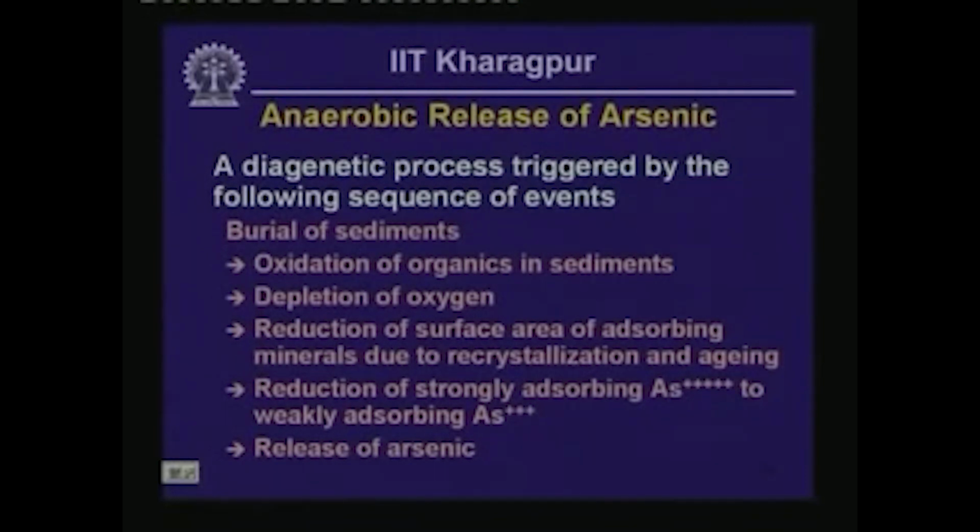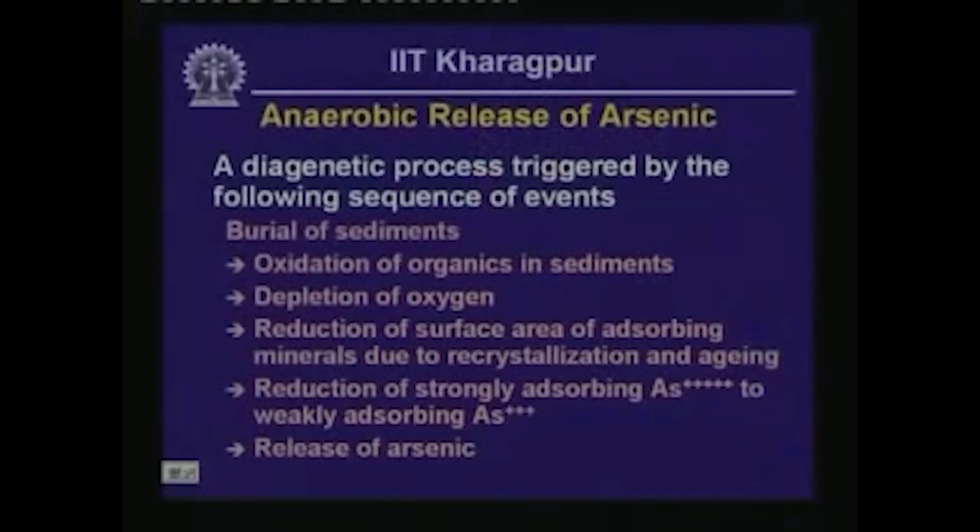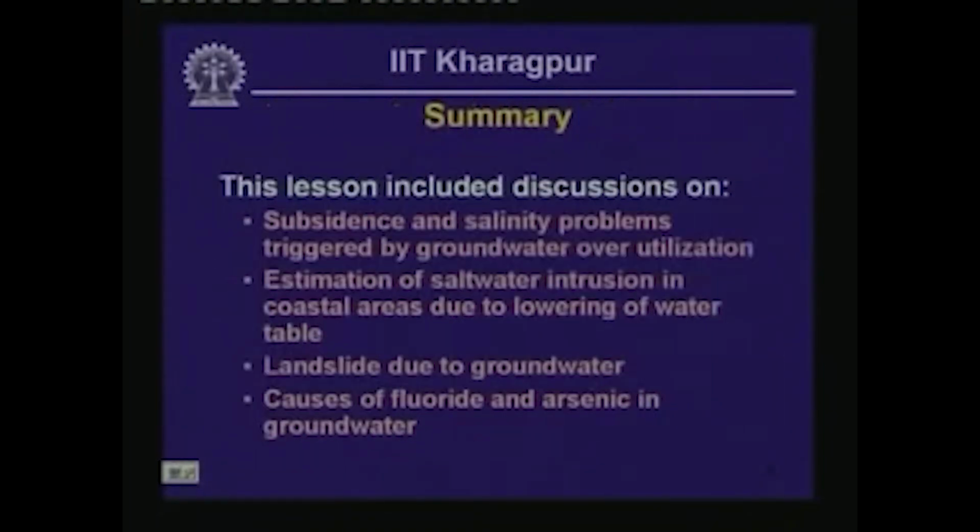And because the lower reaches of the Ganges-Brahmaputra delta are also affected by a very low hydraulic gradient, or very slow groundwater movement, the arsenic that is released accumulates within the groundwater. So the problem doesn't go away very fast, and it remains a problem over a relatively long duration.